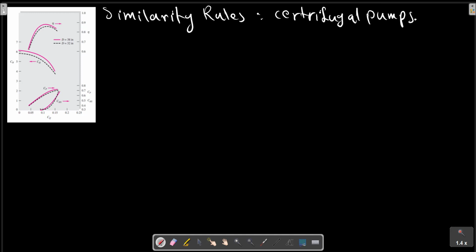The success of this picture as the similarity non-dimensional numbers in pumps correlate pump data leads to a simple rule for comparing pump performance. If pump 1, for example, and pump 2 are from the same geometry family and are operating at homologous points, the same dimensionless position on a chart such as this picture, their flow rates, heads, and powers will be related as follows.